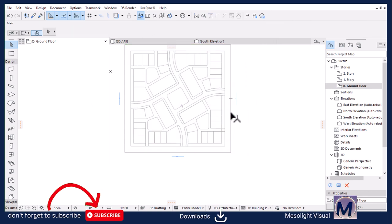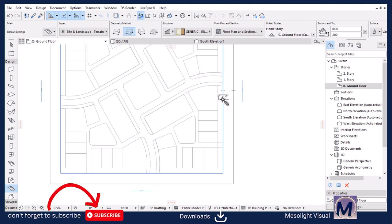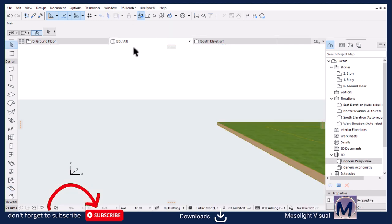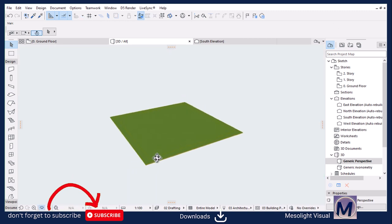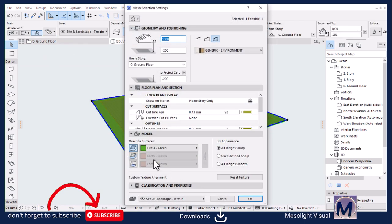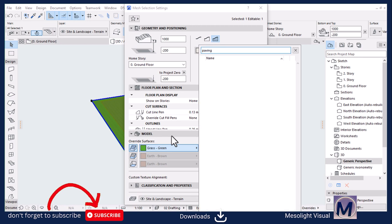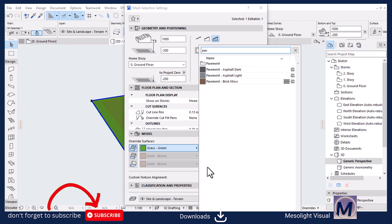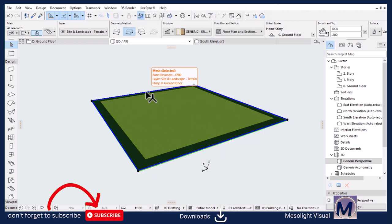So I'm going to apply another pick parameters of the mesh again, and then apply it on the internal line, so that when you see it in 3D, let me just use this fit window to fit that. When you see it in 3D, it's like this. But this one is a road, representing a road. What I would do is change the surface to paving. Go for paving, asphalt, dark, and then I'm going to create a layer that will represent that.